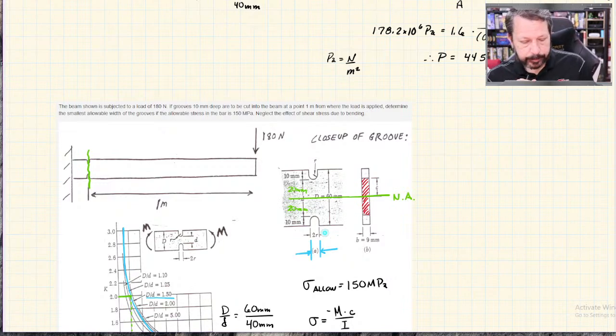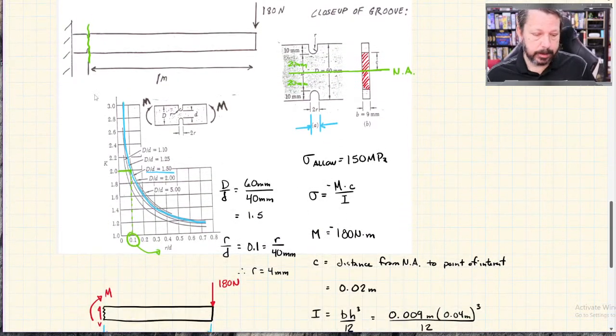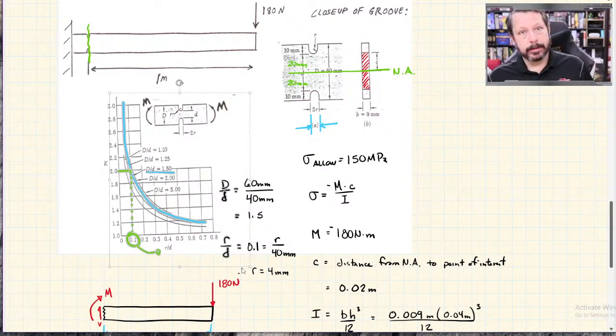So the general idea: you calculate, like you've been doing, the base stress, the average stress. So either force divided by area, or MC over I, or T rho over J, or TC over J, whatever your base stress is. And then you multiply that stress by a stress concentration factor, which you get from one of these charts knowing the geometry of your part. And that's your new stress. That's the stress that would be located at that stress concentration.